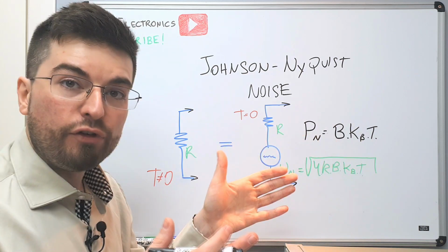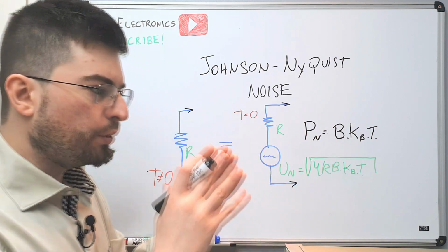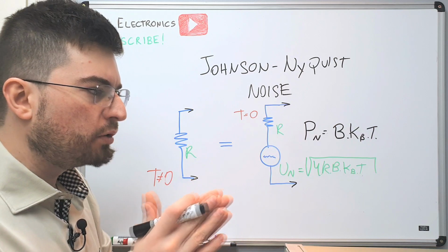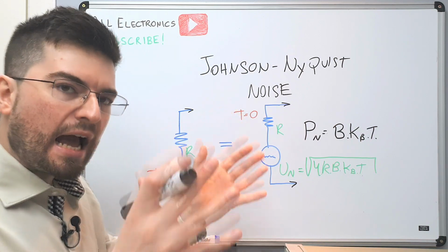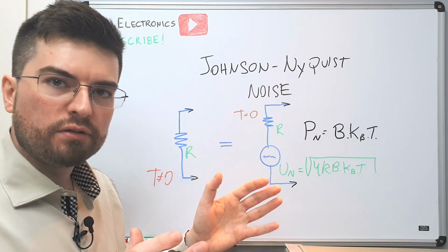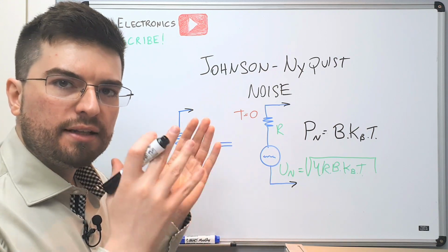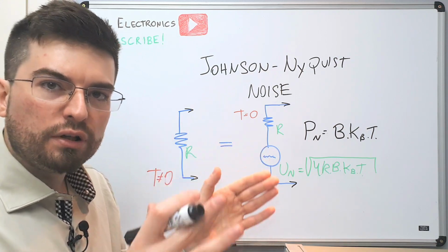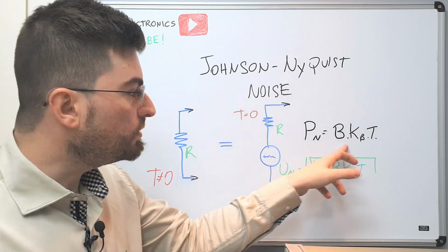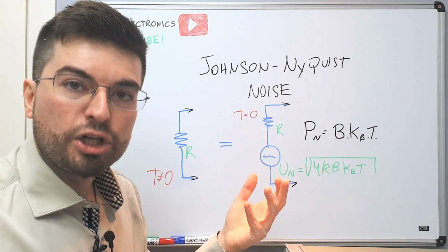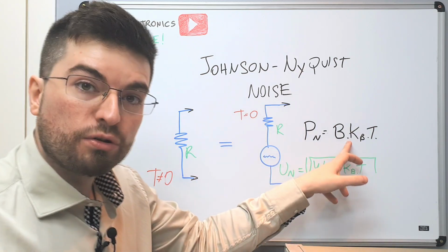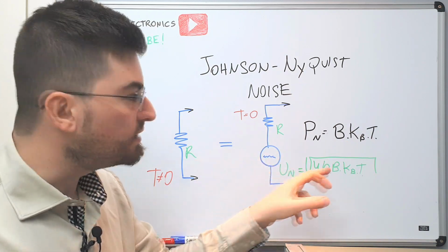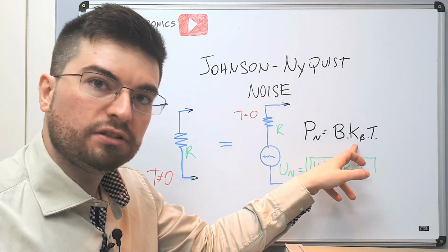The bandwidth is a function of the system. So we have a system with a modulation bandwidth. We are going to design our receiver front end around that bandwidth. The antenna, the amplifiers, the filtering is around that bandwidth. Boltzmann constant is a definition of the universe. It is a constant. So if the bandwidth of the system is fixed, we have a constant here.